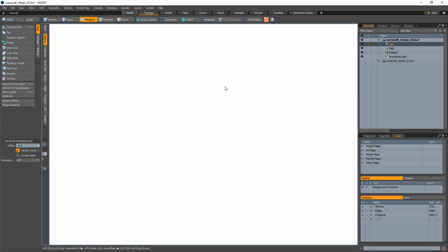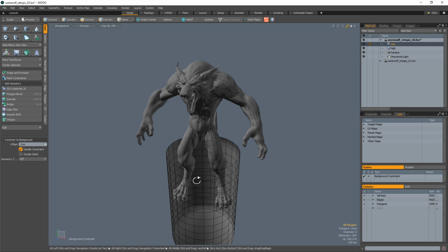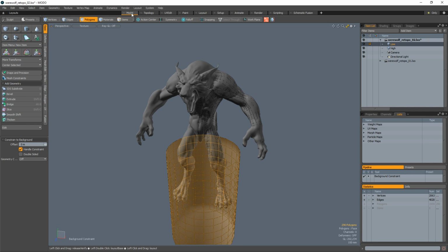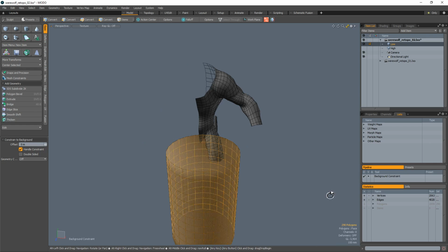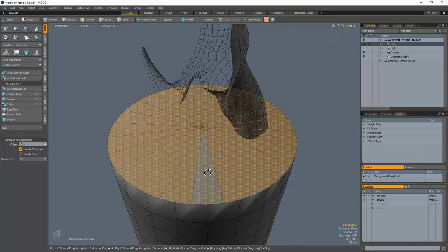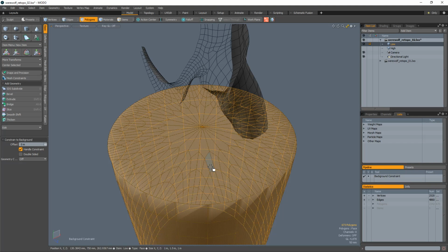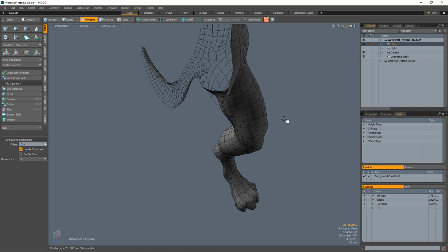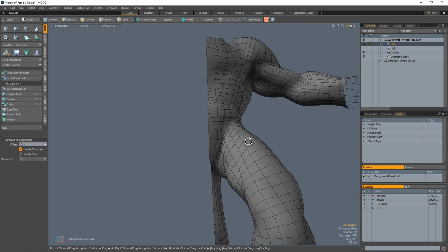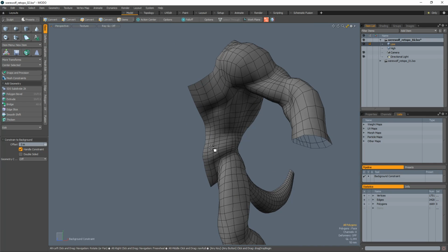So, for example, if I just make a cylinder right here, this, depending upon the program that you're using, might subdivide in different ways, but that's really the only type of case that I'm aware of where it might spit out triangles. And yes, it'd be useful to test that out in Max, Maya, whatever program you're using, just to make sure that you know exactly what you're running up against.